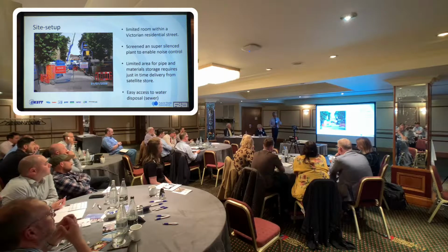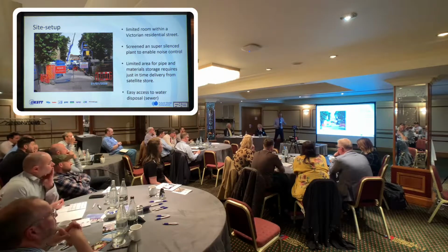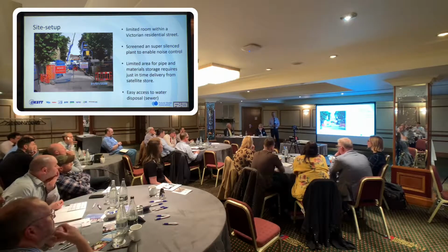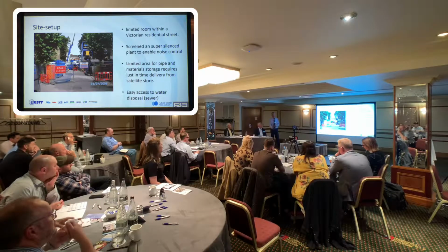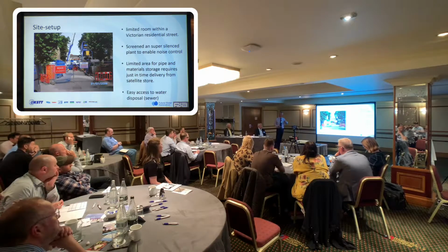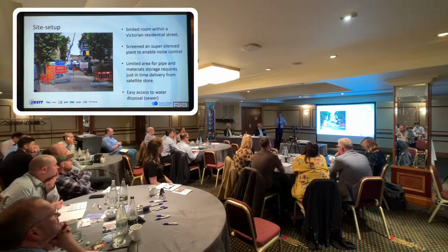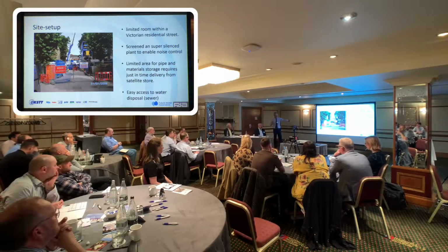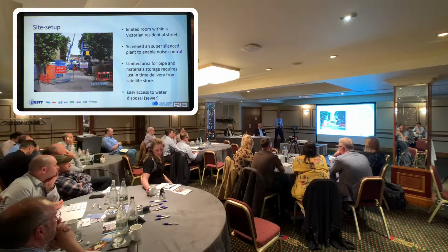etc. But again, site wagon movements are exacerbated by this site because you've got to deliver pipes just in time because you haven't got room to store them, and for spoil, you've got nowhere to keep that either, so you've got lots of wagon movements to manage. So in terms of an environmental impact study, whilst pipe jacking reduces your impact to localised working areas, you've still got all of those plant movements and wagon movements to deal with.